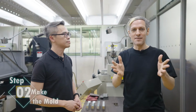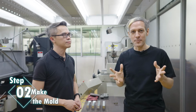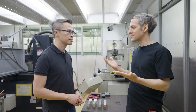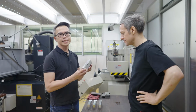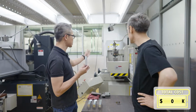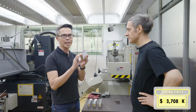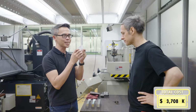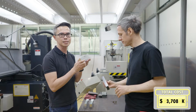So you've designed the mold, you've designed the tooling paths, how you're going to cut all the parts, you've ordered the raw material. What happens next? So the next step, we will put this raw material onto this grinding machine. The grinding machine will make the cube perfect, super flat, super precise, and so we can put it onto the CNC machine for the next step.